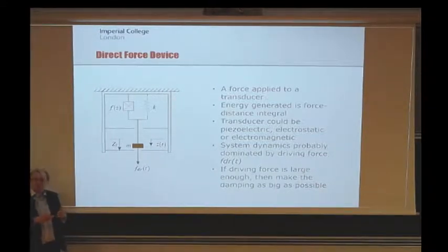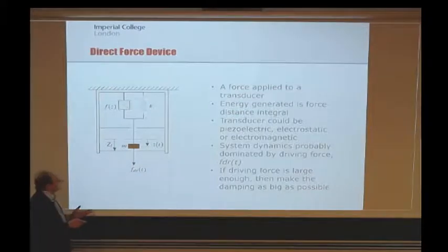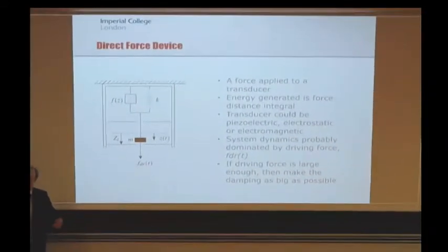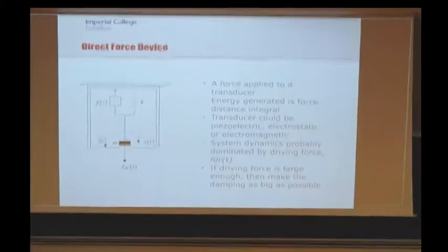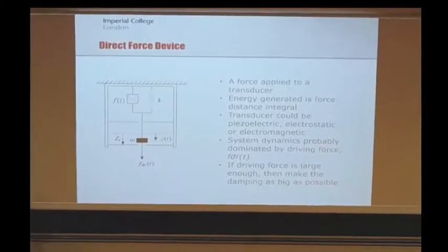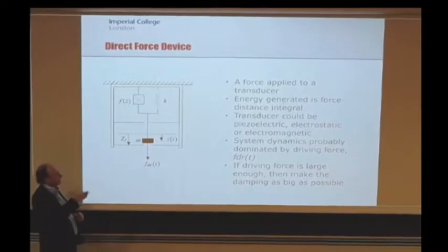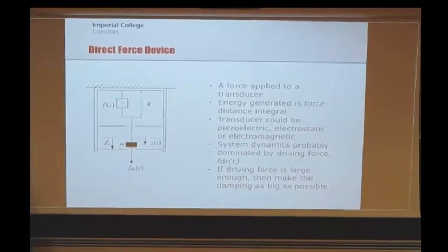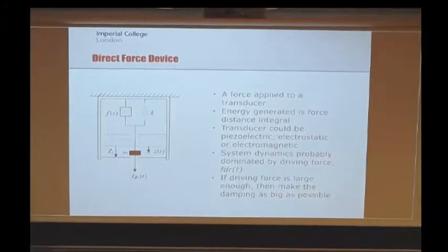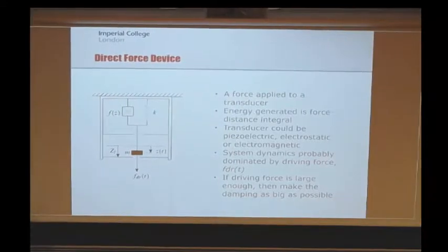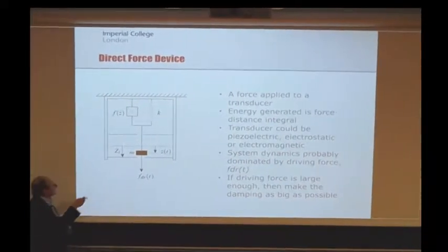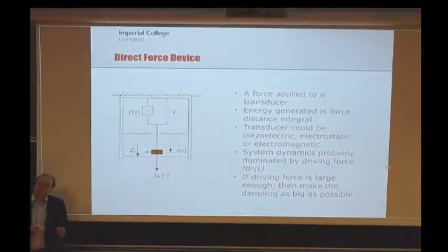And of course ultimately, if you think about the conversion here from the mechanical domain to the electrical domain, then really I'm interested in integrating the force with respect to displacement. So the bigger I can make the force, then the more energy that I can get. And of course, as I said to you, I'm going to be limited in terms of size, so the displacement, the travel of this, is going to be relatively limited. In a MEMS device, the movement that I can get on the transducer is going to be perhaps hundreds of microns, perhaps up to a millimeter, but it's going to be small, and so maximizing the force is very important. And with a direct force device, potentially I can do that. Once I rely on inertia, as I said, the force is going to drop off considerably.